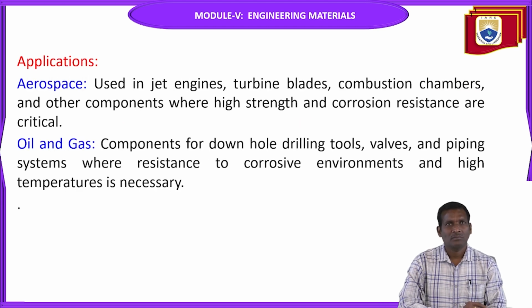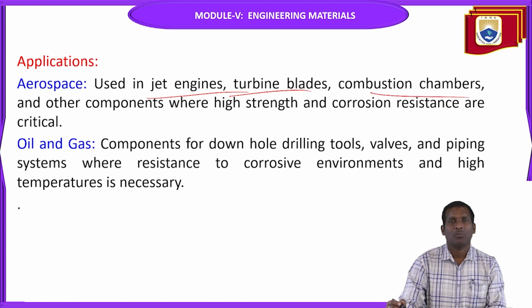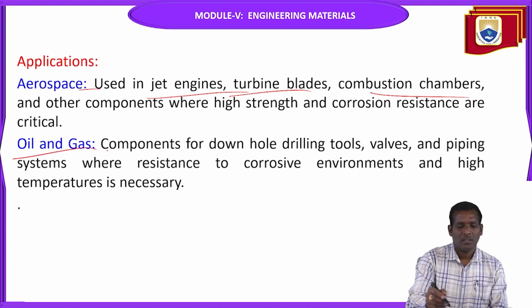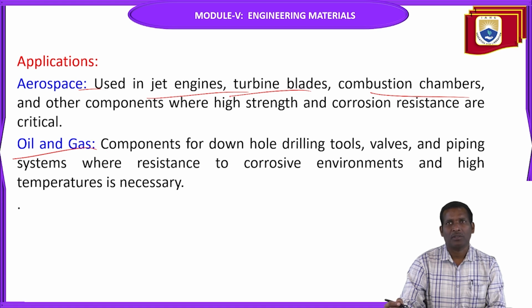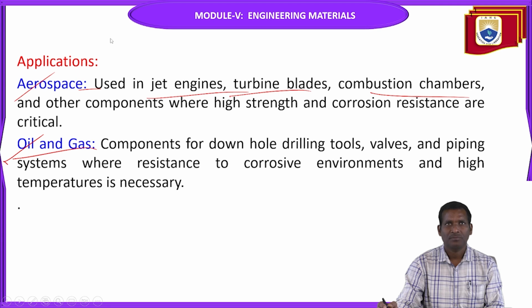The applications: aerospace applications, used in jet engines, turbine blades, and combustion chambers, and other components where high strength and corrosion resistance are critical. And oil and gas: components for downhole drilling tools, valves, and piping systems, where resistance to corrosive environments and high temperature is necessary. So these nickel-based alloys are used in oil and gas industries and aerospace industries.